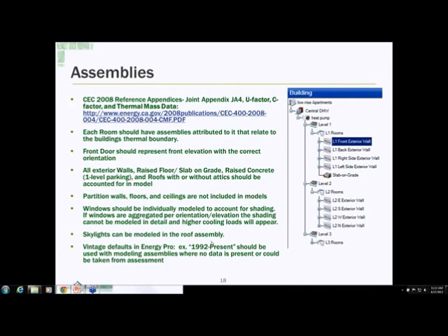I have one question: I always get an error with more than 6 bedrooms in a home. Is there a particular reason? So the error messages, you can ignore that unless it stops you. There are 2 types of error messages in Energy Pro, one that actually stops you from running calculations, and one that's just kind of like, hey, you have more bedrooms than what's typically found in a residential building, are you sure this is correct?